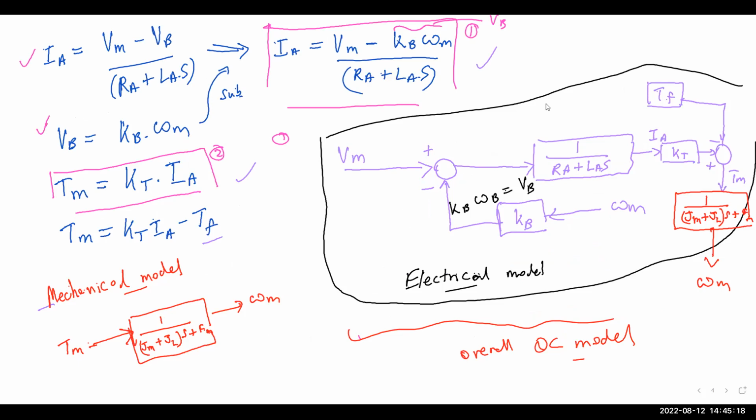So simply you just have to go to MATLAB, make the block diagram in this form, give inputs, and see whatever outputs you can obtain. You can obtain outputs for omega m, right? You can vary these inputs. System parameters are obviously the same, right? So you can see how when you change the terminal voltage over here, how the omega is going to change, how the torque is going to change over here, right? So you can simply check all these. And this is omega m.